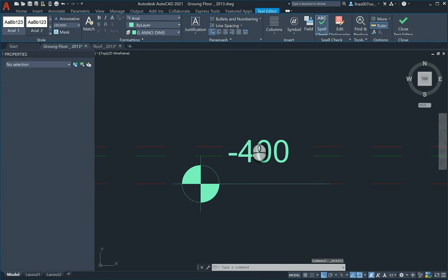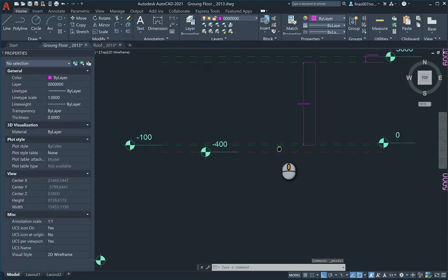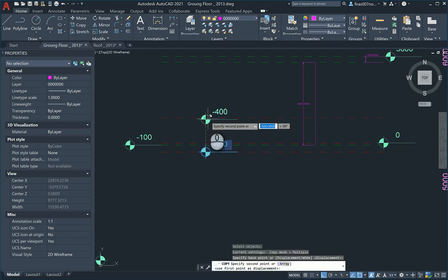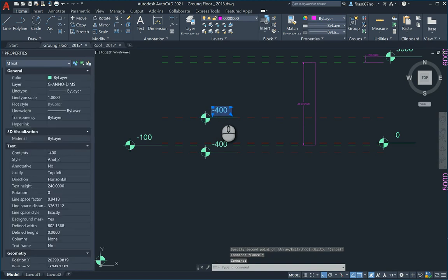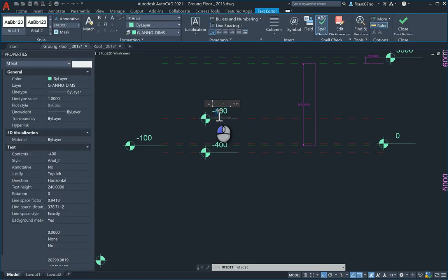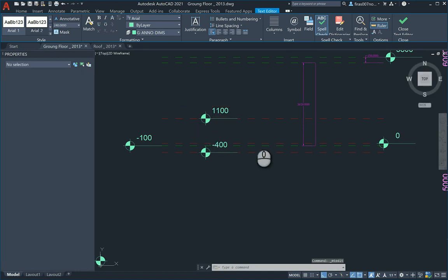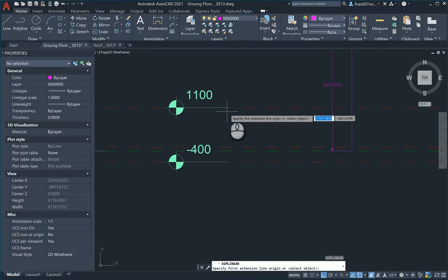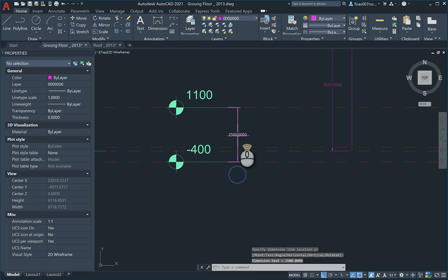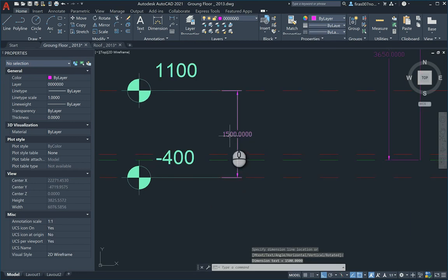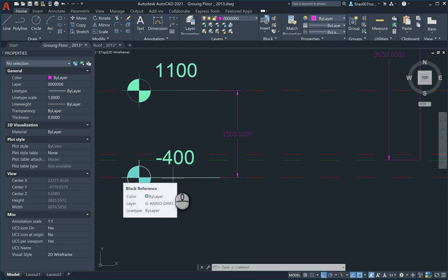So double click and change that 100 to 400. Now the top part, as I said, it's 1100 from the 0, so this dude is just 1000. Probably drawing this section makes all the annoying part of guessing and mathematic things that I saw lots of students messing up with it. Just now dimension them, you know. That will be the Z value, so 1500. Sorry, that will be the extrude value, 1500, and the Z, as we said, will be the lower edge, which is the minus 400.